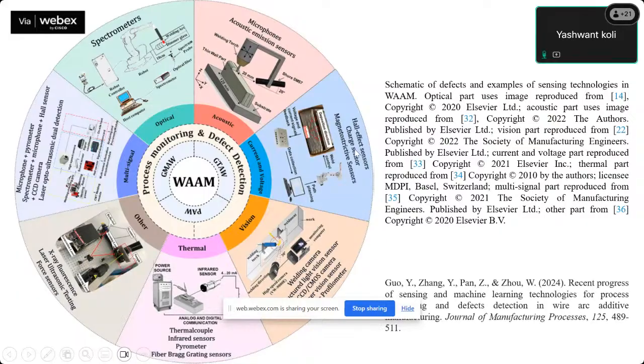So the other defects, like geometric irregularities or geometric deviation, are formed from high energy heat input and unstable arc. So unstable arc and high heat input are the main causes that form many defects. If we can control these things, we can get a very good product. Then residual stress is also a problem that leads to distortion, cracking, and delamination.